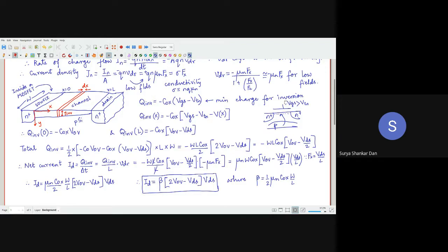But the problem is, what Ashok is telling is, if you are applying a minus VG, obviously this is going to be less. Then what will happen? You are not going to do any depletion there. You are going to have more holes on the surface. Then what is the situation? You are applying a negative charge and you are having a plus over here. So this kind of operation is called accumulation mode MOSFET.